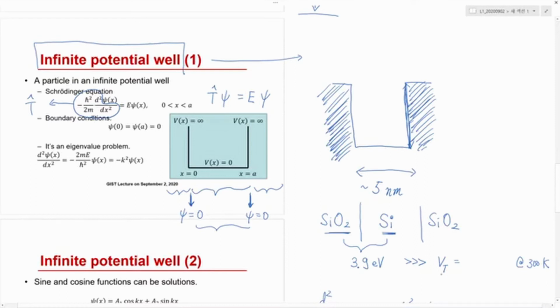This is the thermal voltage, so in order to get an energy in electron volts, we have to say q times Vt, or kT. Yes, this is the thermal energy, and the thermal energy at 300 Kelvin is about, as Mr. An correctly answered, 25.85 milli electron volts.